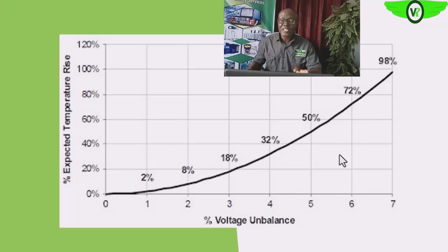So you check the unbalance at the input, and that is at the input into the motor system. That is the input into your circuit breaker or into your fuse. Okay, into your fuses at the MCC. And then the input into your motor at the terminal block of the electric motor.